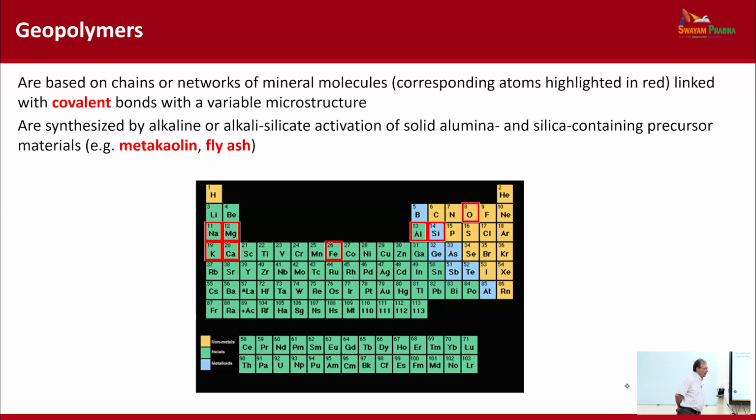One interesting feature of geopolymers is that you do not need to start from a clay to obtain a highly reactive aluminosilicate material. For instance, you can use fly ash coming from coke plants, from electricity plants using coke. You can use other sources coming from waste that contain aluminum and silicon, like metallurgical slags, which are reactive because they are amorphous.